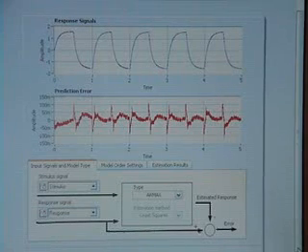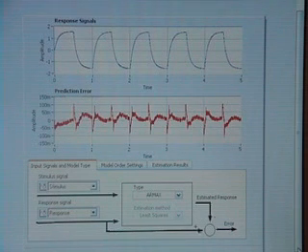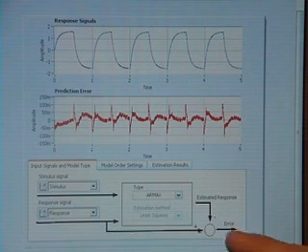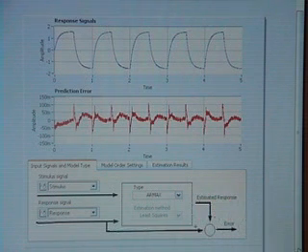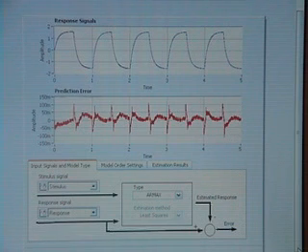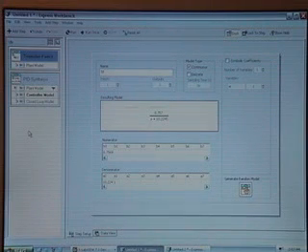Okay, so here we're showing the system identification software, which will allow us to create a model for our DC motor. It takes the incoming step response signal and allows us to vary the type of estimation that we're going to use. We can change the different orders for the coefficients, and the result of this process, of course, is an actual transfer function that we can use to model that system. The next step is to do the control design.